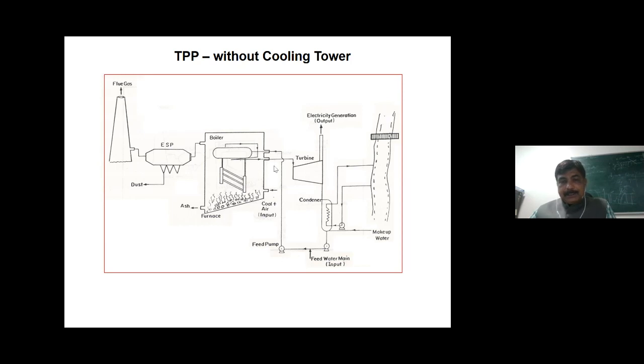this boiler. Now how can we take it back? We need to liquefy it because steam cannot be pressurized. Our pumps will not pressurize it. We need to bring its temperature down. How to bring it down? Here is the condenser, in which you can see from the river we are taking cold water, circulating it outside in a jacket, and then, so what happens here?